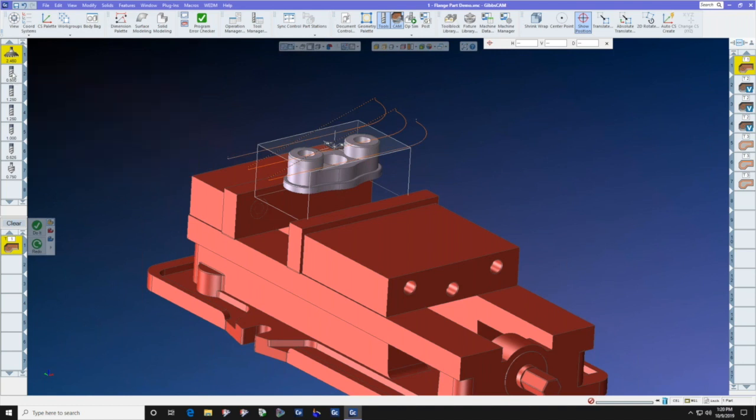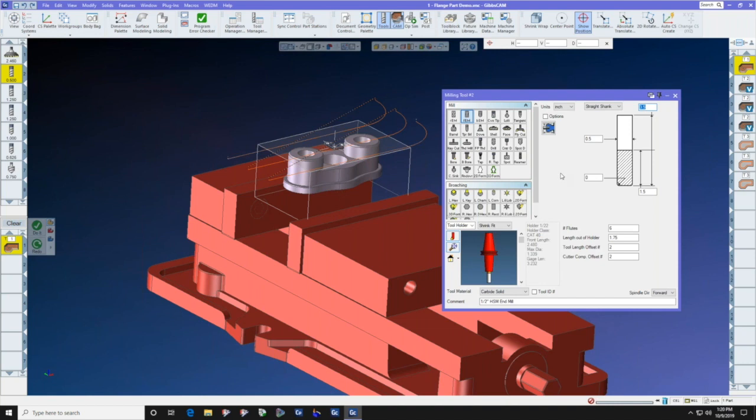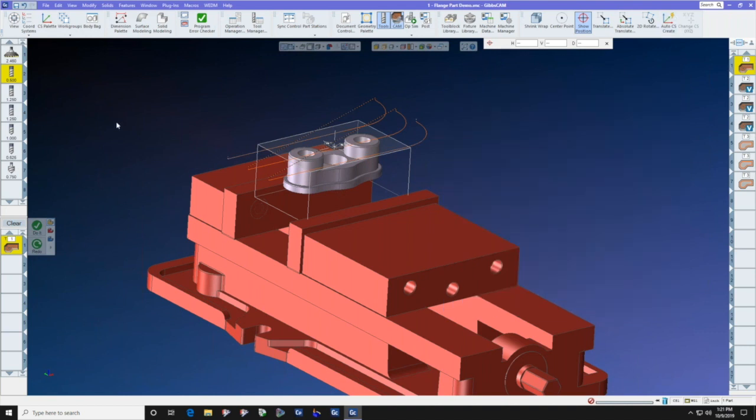So we have a high-speed machining end mill. What are the characteristics? Usually has no more than 3 times its diameter in flute length. It has 6 or 7 flutes, a 45-degree helix, and a special coating, usually, and in this case, today we are machining 17-4 PH with a Rockwell C of 38. So we're going to have AlTiN coating on our end mill to do the high-speed machining, AlTiN.